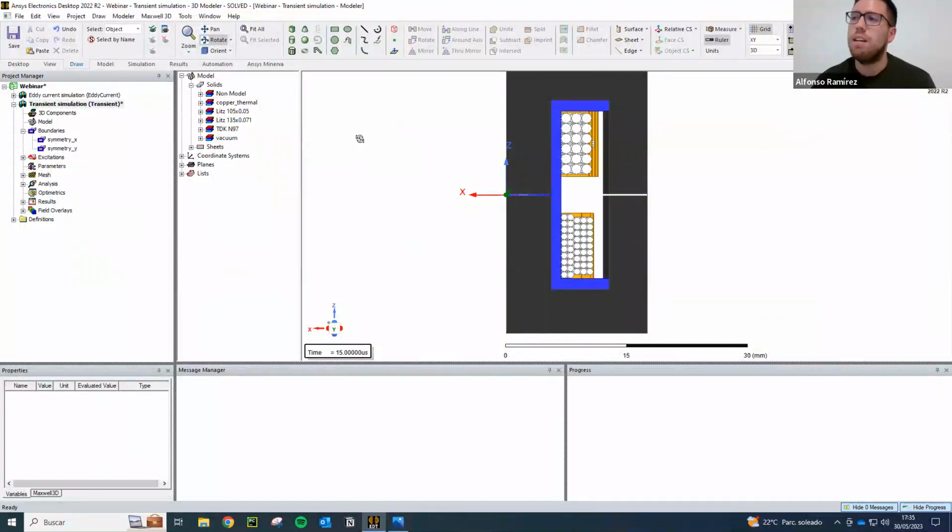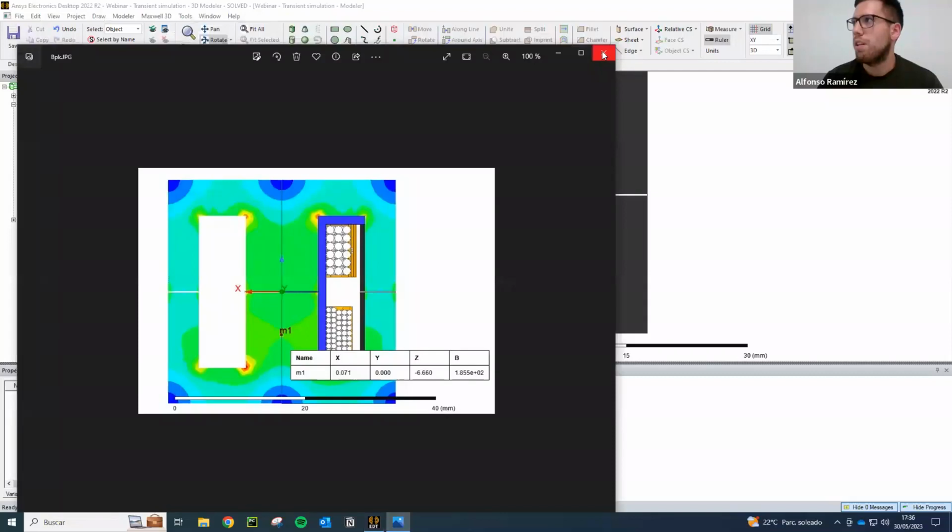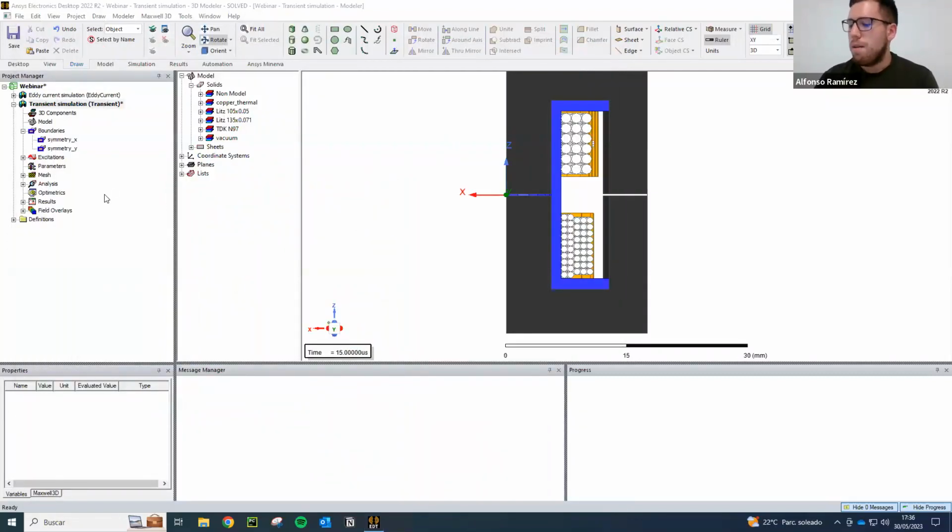And I would say that I think it's a very good combination. The things that you can have with ANSYS, like plotting the fields, H field and B field, is something that we really like when we want to know, for example, how the gap is going to affect the whole structure, or which points can be affected by saturation. For example, we can see here the corners are kind of saturated, but it's not something that is going to impact our magnetics. And that's it, I would say.